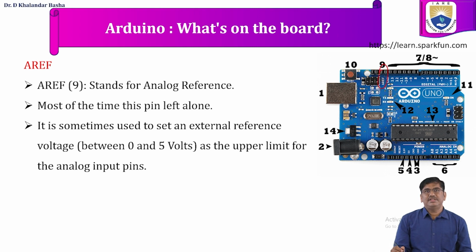So this AREF stands for analog reference. Most of the time this pin is left alone. It is sometimes used to set an external reference voltage, between 0 and 5 volts, as the upper limit for the analog input pins.